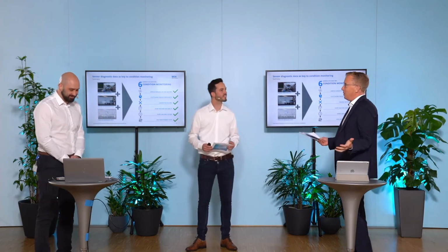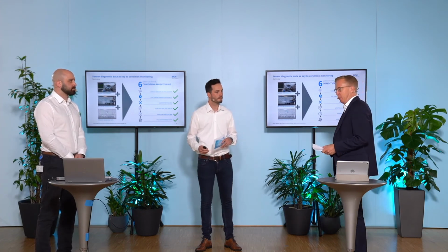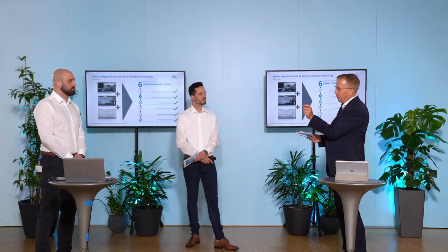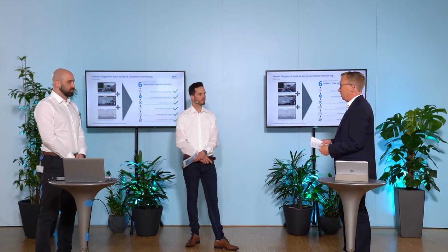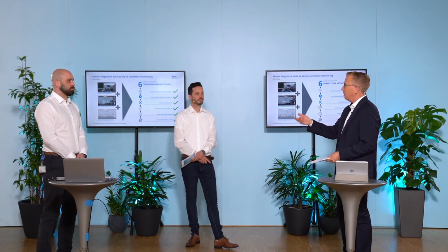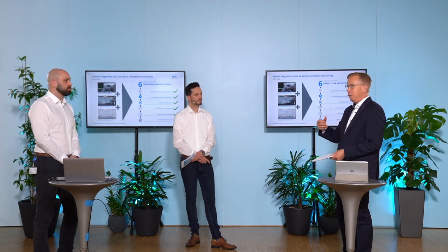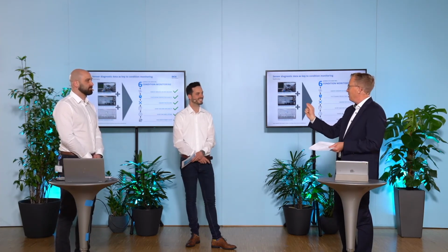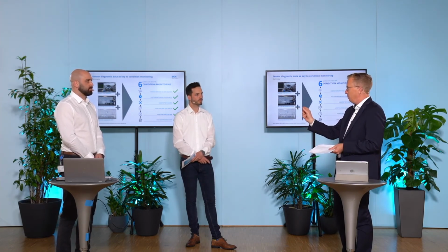Yeah, thank you very much. Now I know why you guys are so excited about cylinder switches. It's pretty amazing. What I took away from it is that, yes, you can detect whether it's there or not there, or what position it is, but on top of this you have the analog values, and at that position you get quality information about the run health of the machine. So yes, we're not going to complain if you just use it as a normal, simple sensor, but there's so much you can get from that position to increase the availability of the machine. So now I understand why these guys are excited.